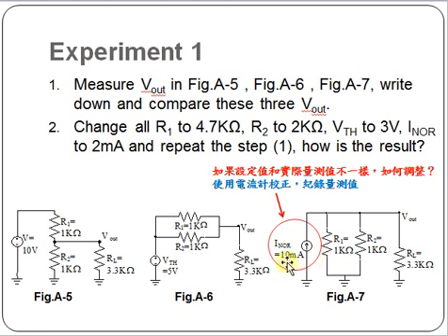Here you can see that there is a current source. How do we implement a current source? Use the current limit function in the power supply. Set the current limit to the desired value, in this case, for instance, 10 milliampere. Then turn the voltage higher than the value required to generate the current.